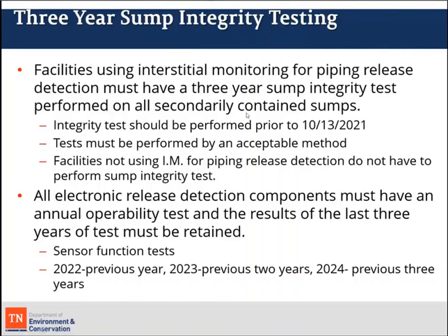I've been trying to get that out to different owners and contractors, because there does seem to be a little bit of confusion. Just because you have a sump present doesn't mean you have to perform this 3-year test on the sump, only if you're utilizing that sump as a component of release detection, i.e. interstitial monitoring.